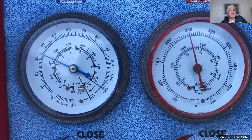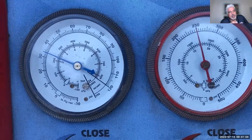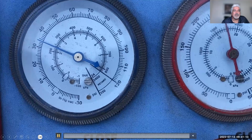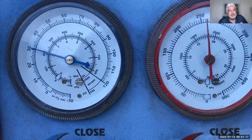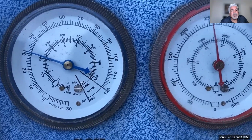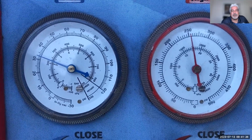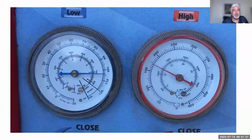But again, what I'm trying to show you in this video is that the TXV should be regulating that flow, indicating to you on the low pressure side that the pressure rises and drops just like you see there. Hopefully that helps you get a visual on what you're looking for on a thermostatic expansion valve system. Make sense? So this is definitely a good TXV that I see open. That's normal to see. Hopefully you can see that on the video. So there you go. All right, let me go back to where I was.